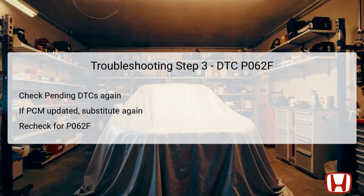After addressing the PCM update and potential substitution, this step focuses on re-evaluating the situation. Begin by checking for any pending or confirmed DTCs once more using the HDS. Monitoring the DTCs after any interventions helps identify if the steps taken were successful in rectifying the issue.